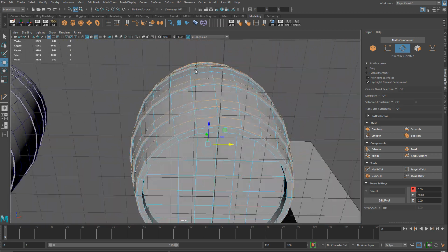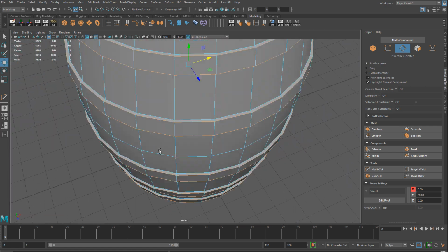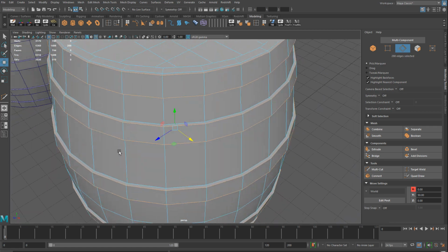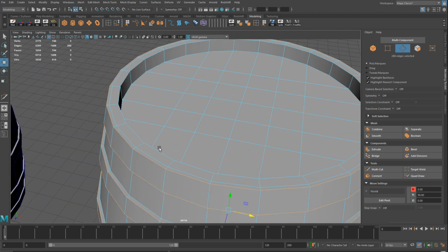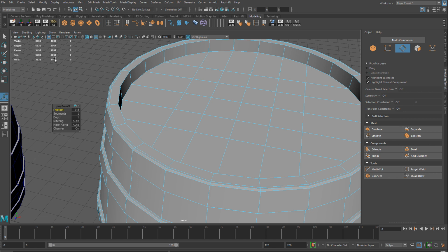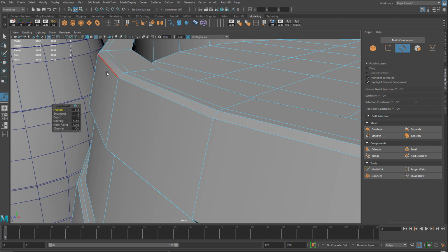So I'm just double checking. I selected all my edges. The thing about beveling is make sure you select your edges. If you miss one, then you create issues you have to fix, which is more time consuming. So I'm going to go ahead and hit Control B. So it jumps me to over 2000 triangles. I'm going to come over here and you can see that I created a slight corner. Maybe I'll adjust my fraction to 0.4. Let me see, 0.2 might be too small, 0.3. Let's do 0.4. Actually, 0.3 I think looks good.